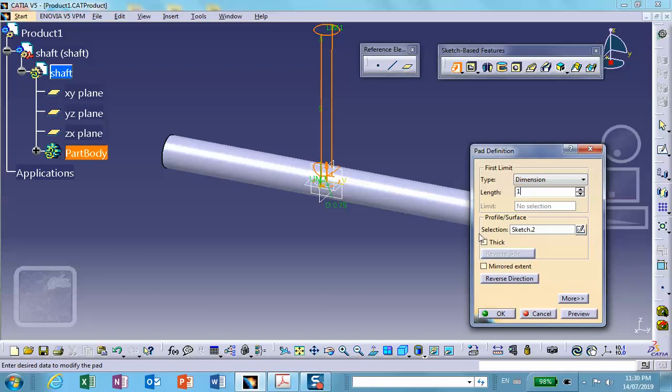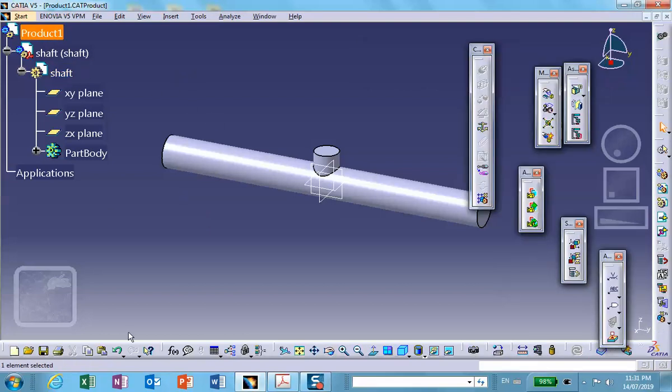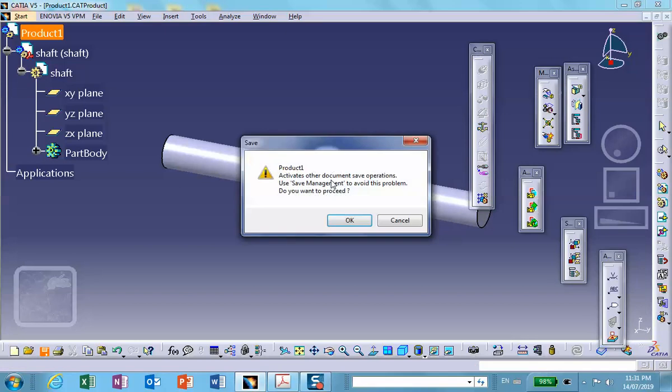Let's see what happens. Yeah, and I will apply the load that the book says is 1,000, but I told you I was going to use 200 on that shaft. This entire assembly is made of aluminum, so I thought 1,000 was going to be a large deflection if you use aluminum. Alright, good. So now we're going to immediately save this and insert our left bearing.